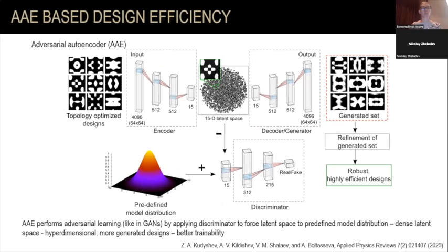So what we found works better is the so-called adversarial autoencoder, which means that you're not working with the design itself, you actually compress the representation into the so-called latent space. By reducing dimensionality, you perform a much better search, and you can also introduce some limitations and constraints into the latent space that make it possible to search really fast, to search in hyperdimensional space. So you can actually introduce many parameters in optimization. Remember what I said, with direct optimization, it's hard to change several things.